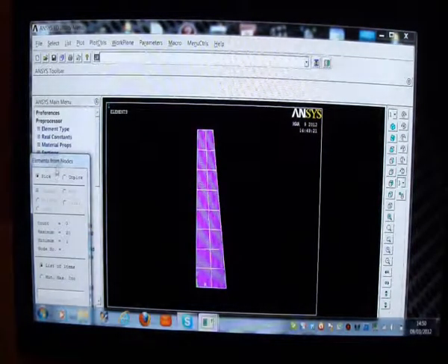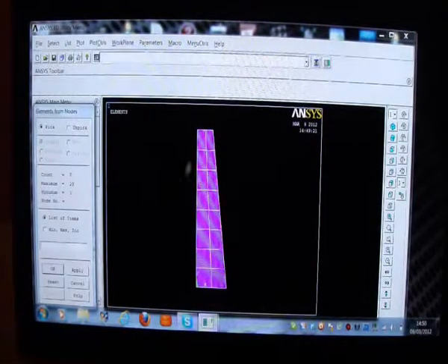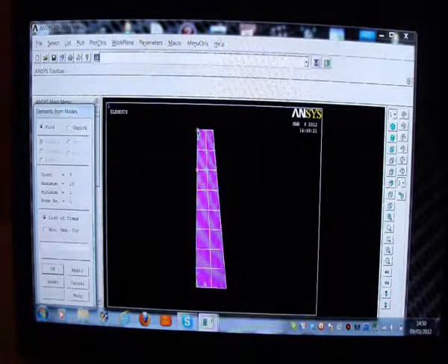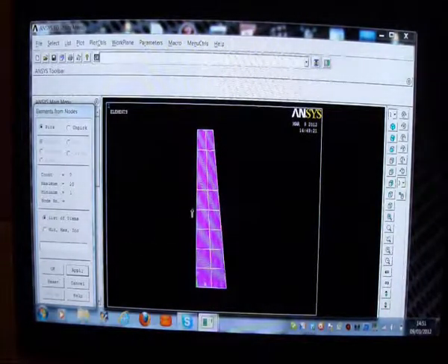I'm going to put my beams now, and I pick on a beam here. That's the I and the J of the ends of the elements, and the K represents a triangular plane about which the beam bends. I then pick on I, J, K, and remember I, J, K represents a triangular plane about which the beam bends.